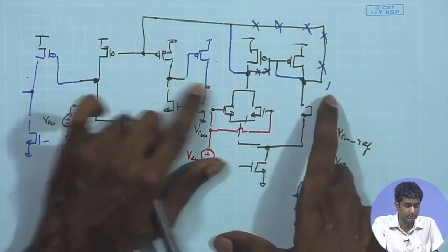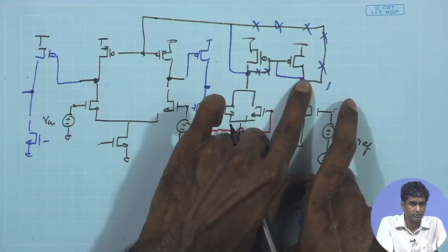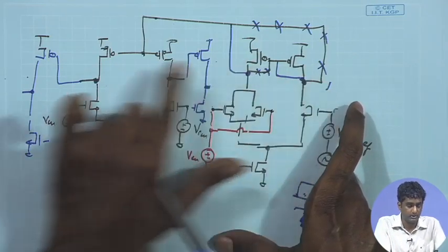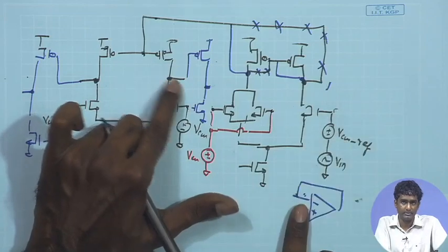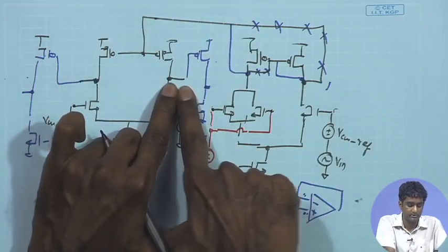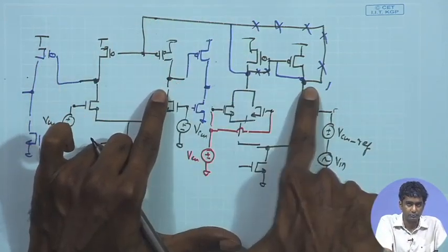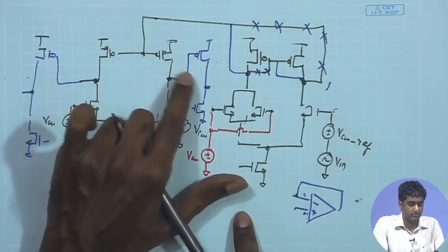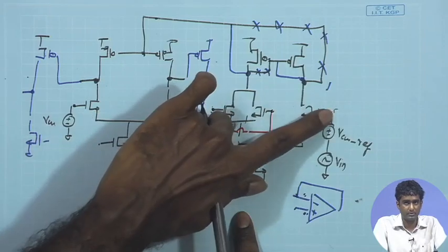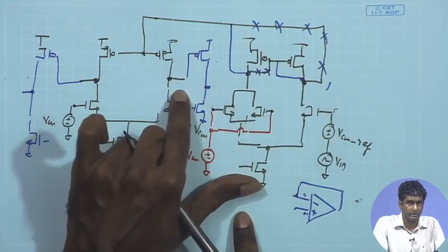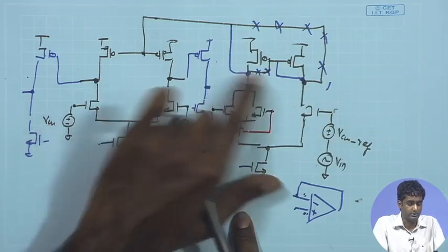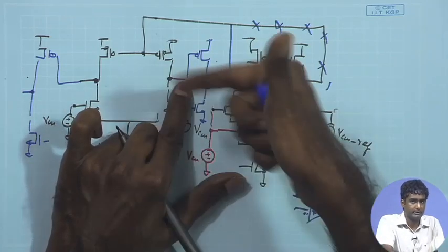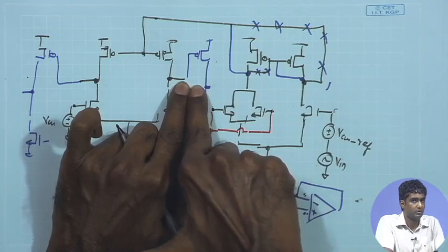That will basically introduce the Miller effect here strongly. So that will try to have a large effective Miller-multiplied compensation capacitance over here, but you don't want that Miller-multiplied capacitance over here, because in the closed loop, that capacitance also comes between this point and this point, and we are having a signal path from here. So we discussed, let us have a buffer and then connect the capacitor between this point and the buffer output at the first stage, so that the buffer output has low impedance. Even if there is a Miller effect coming over there, it will not affect.